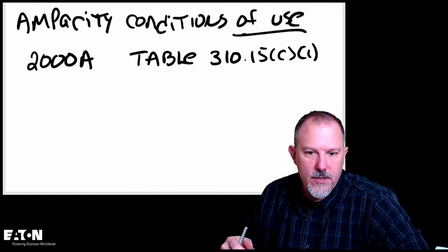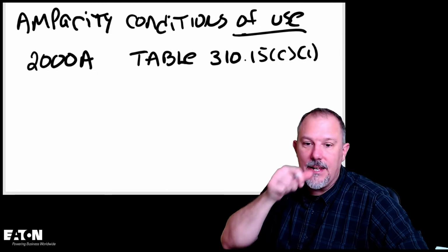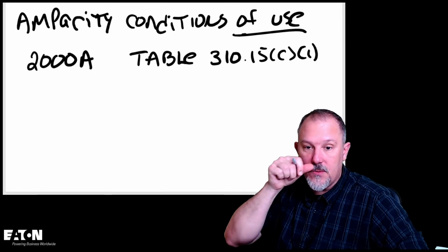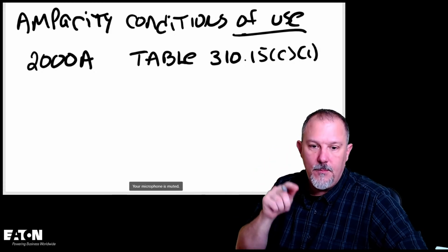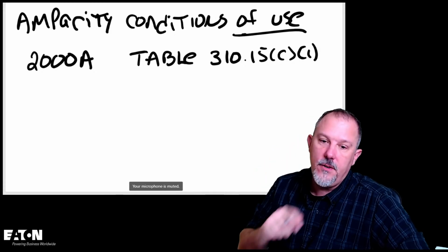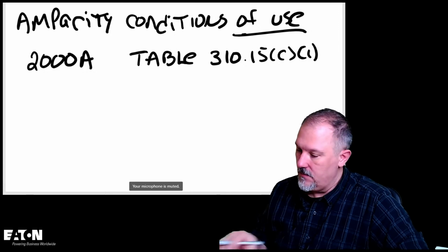Are you installing a wire type EGC? Need to calculate that as well. If using the steel raceway, just use Annex C instead of Table 4. Very good, Ryan. Very good.